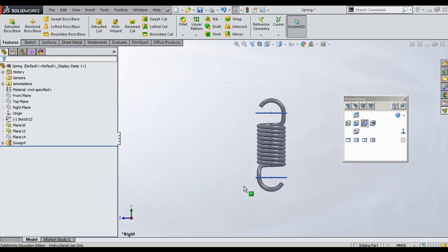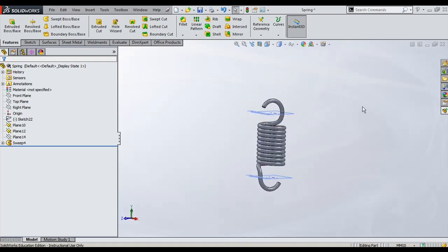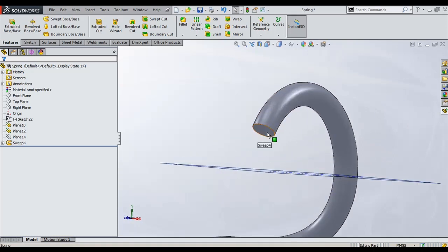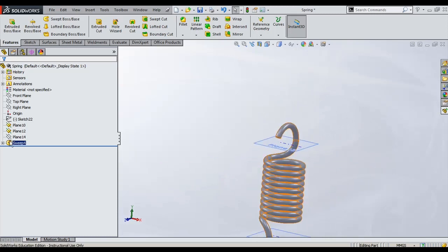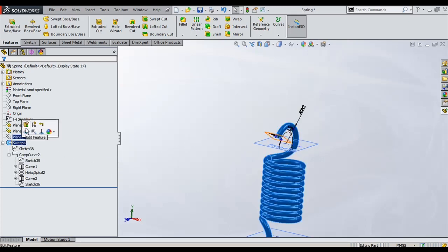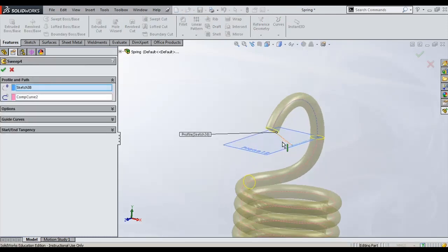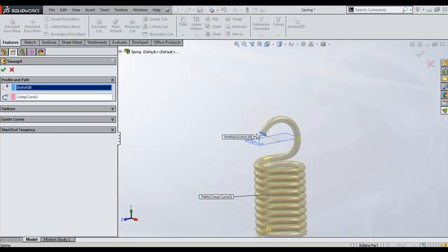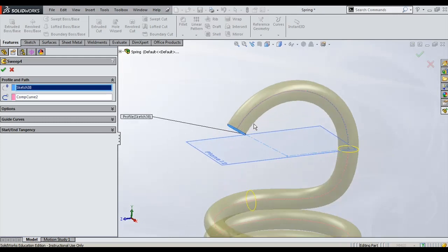So similarly on the bottom face you will draw another arc and the entire thing will be connected, and once you finish this you draw a circle on this end of the curve, and the whole curve is connected using a command called composite curve. So this composite curve will act as one single profile, and in the sweep command you will select the profile. Here you can see we have one profile of radius approximately 30 mm, not 30 mm. I'll show that using composite.